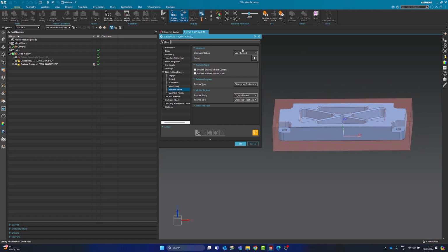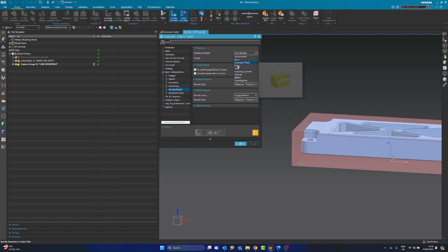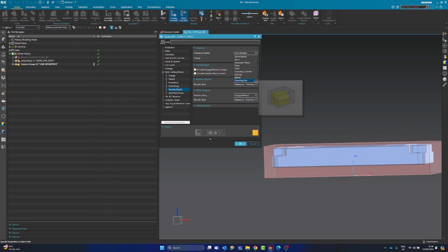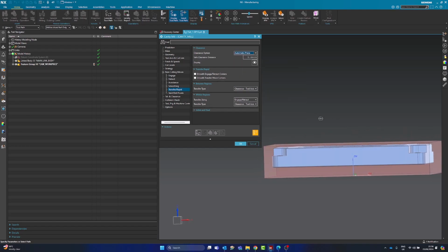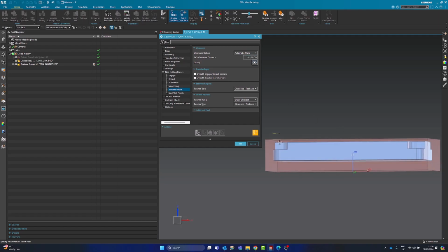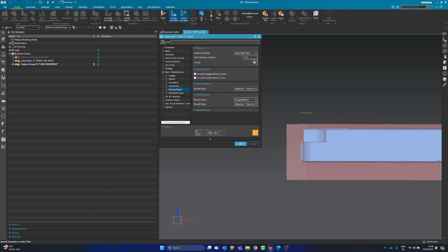So clearance options. So let's go in and set a clearance height. This is going to be how far the tool retracts to. So you can see there's a few options in here. Automatic is normally pretty good, and we'll say 5 mil, and that will take it from the top of our plane here. You can see it knows where the top of our stop block is, so we can say we want to go another 5 mil from there. Let's go 10 mil just to be safe.